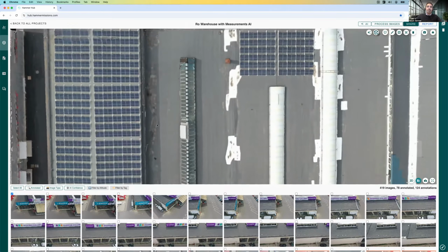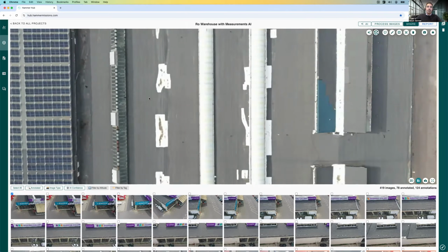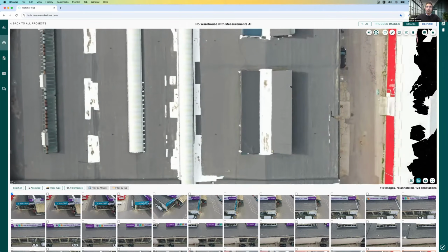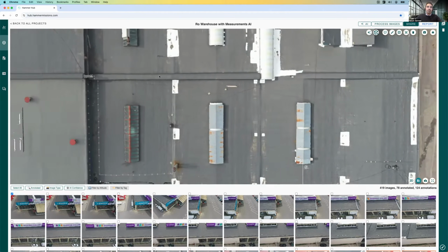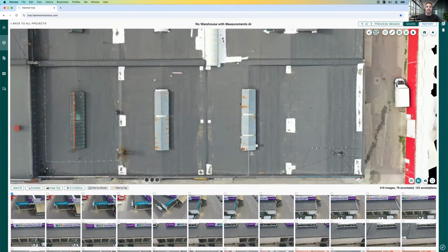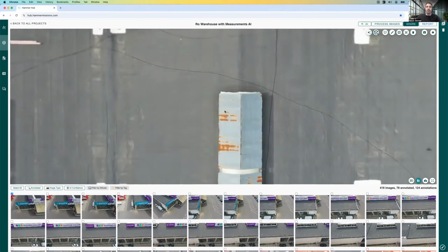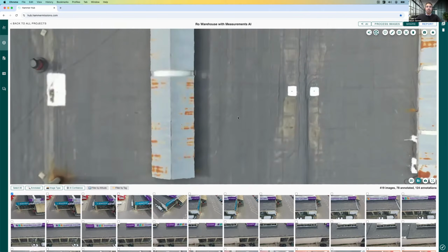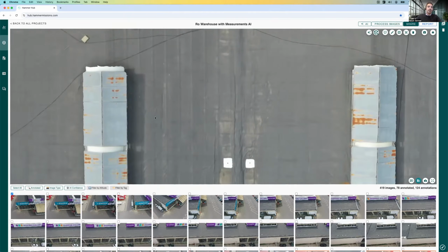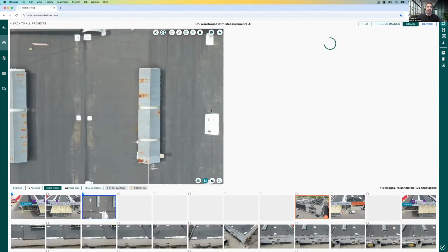We'll do that in just a second, but just to give you an overview, we can still go through the entire roof in the same way and pick up on any things that might look out of the ordinary and out of place. Another thing I can see, if I go into some of these panels over here, is that we've got some rust formation going on, and that's consistent across both of these two panels. If I wanted to document that, I can very quickly and easily just double click on that particular area of rusting.